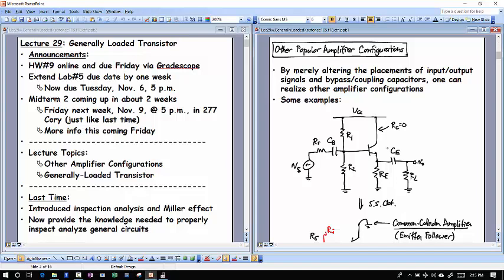Second of all, this transistor circuit that we've been looking at for a while, we can change it into all sorts of different configurations by merely changing the capacitors that we have around the circuit here. And so, for example, if I did something like this, same biasing circuit, you got the R1 and R2 there, you got RE there. I took away RC in this case, and now I'm taking my output here. I've got a bypass capacitor to my output, which has a load resistance. My input's still going into the base in this case, and if I do this,